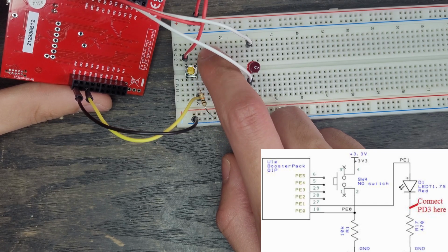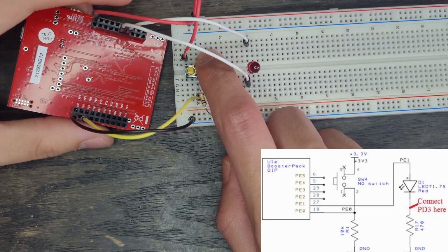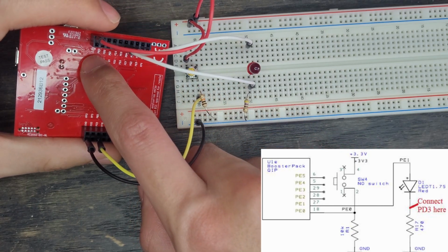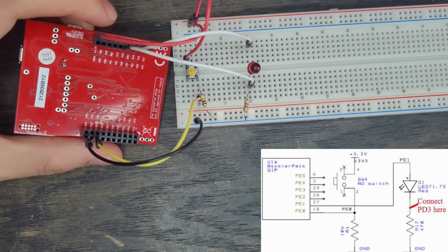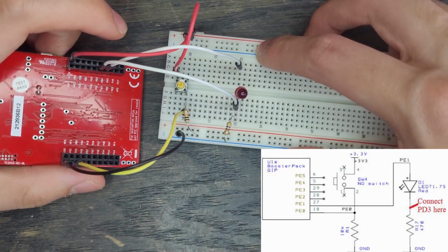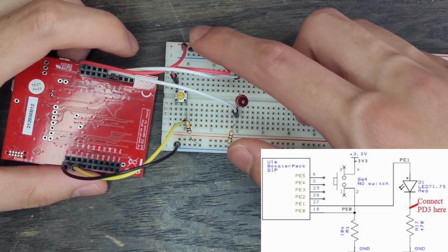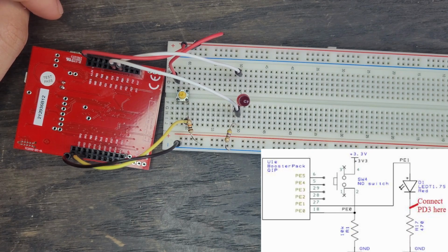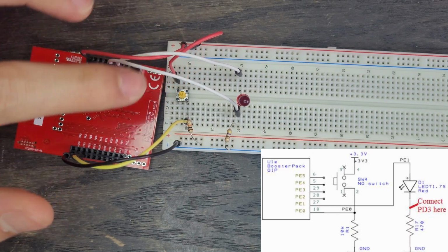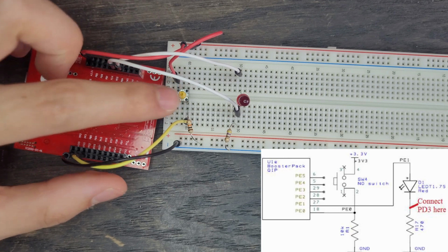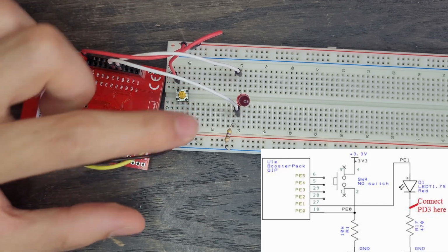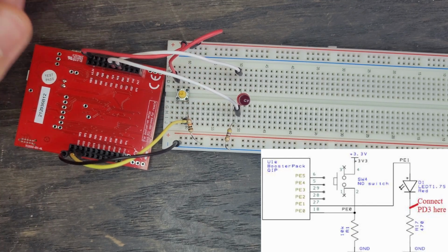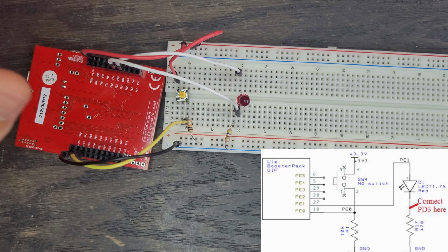And then we are going to plug in a 3.3 volt power supply. The 3.3 volts is up here. So we have this 3.3 volts on the far right hand side. It's going to go into this top rail for power, and then this wire is going to go to the switch. So this is always getting 3.3 volts of power. Now we can allow this power to go through our switch. Some of it is going to go down to ground because of this resistor, some is going to go into the board. And then that is going to output to our LED. That's how the LED stays lit when the switch is not pressed.